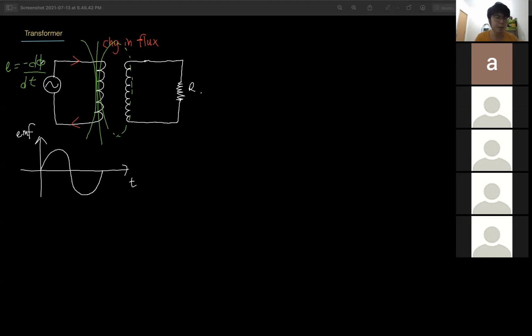This symbol means the magnetic flux. This formula simply means if you have a greater change in magnetic flux, the faster the speed, if it changes very fast, then the EMF produced will be very great. If it changes very slowly, then the EMF produced is only a little bit. So it is proportional to the relative speed of the change. So this is what the equation means.